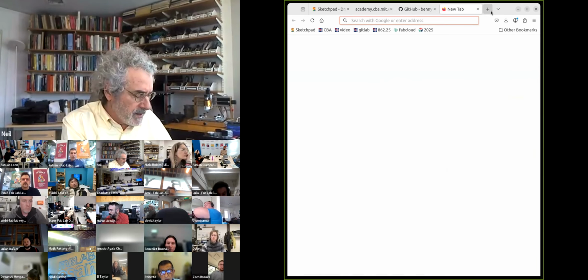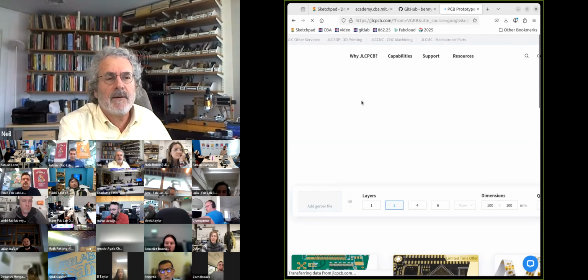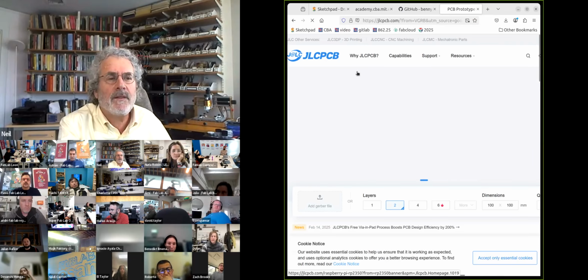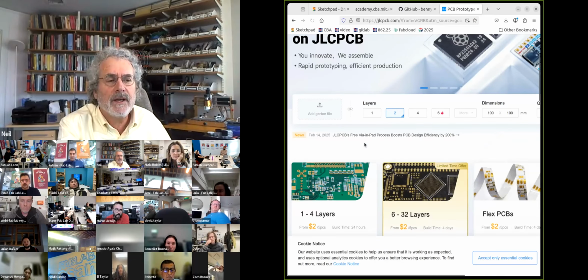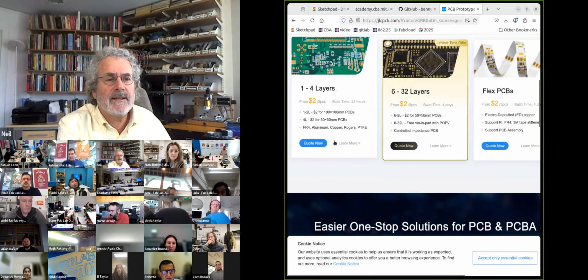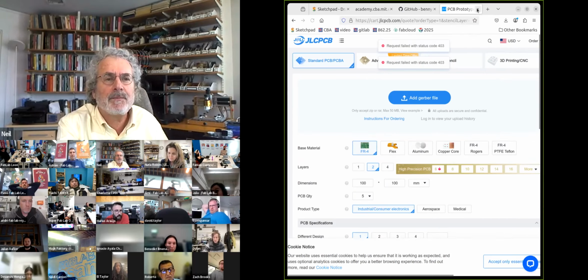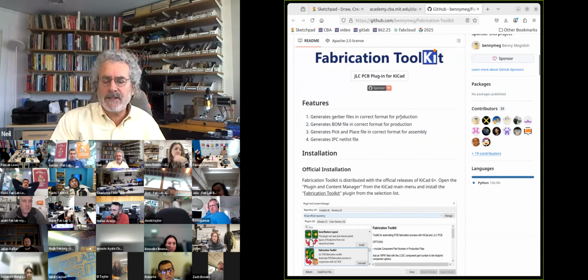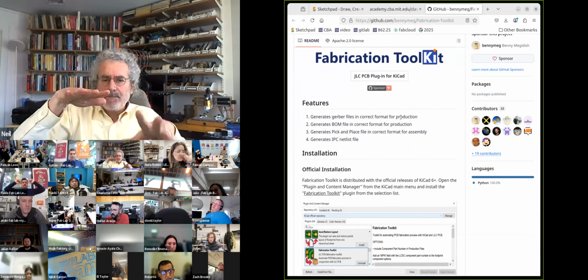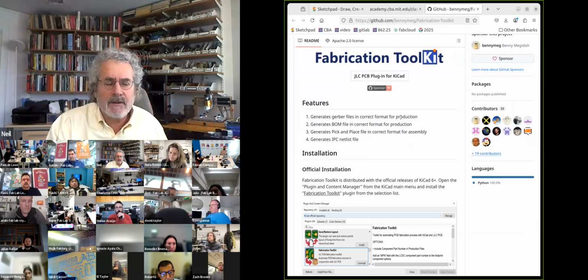the Electronics Production Week. I'll talk about JLC PCB, which is one of our PCB vendors. PCB Way is another one. And if you want them to commercially make a board, you need to upload a zip file that has all of your parts. So there's this link where you need to upload. And so you need to do a production job that exports your top, bottom, drill holes if you have what are called vias that I'll talk about, the silk screen, the masks.